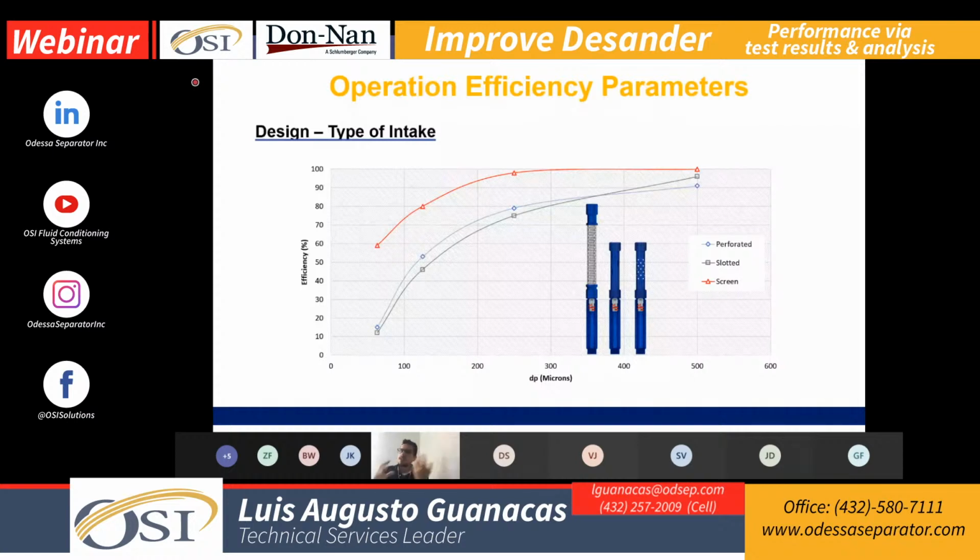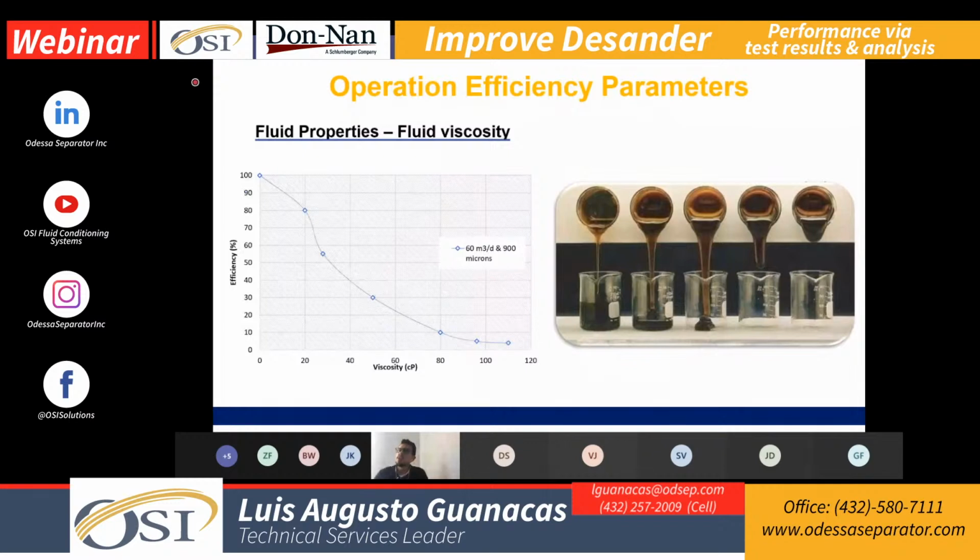Now, previously, we talked about the variables that we use in the design of the tool. Those variables are in our control. I mean, you can choose the material, like Shivani explained before, you can choose the helix size, and you can decide what kind of intake you want to use, right? But the fluid viscosity, you can barely control it. At least you're maybe using different recovery methods with solvent or chemical recovery, but otherwise you have to deal with how it's coming from the formation.